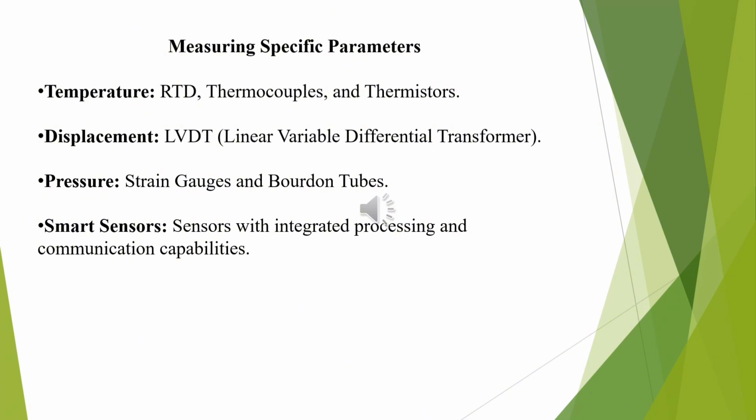The RTD, thermocouples and thermistor are used to measure the temperature. The LVDT, linear variable differential transformer, is used to measure the displacement. Strain gauges and Bourdon tubes are used to measure the pressure. Smart sensor means sensors with integrated processing and communication capabilities.